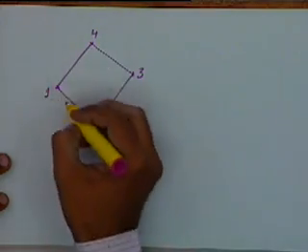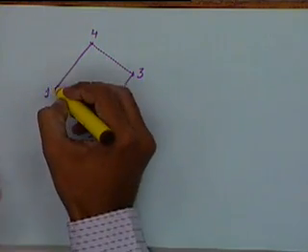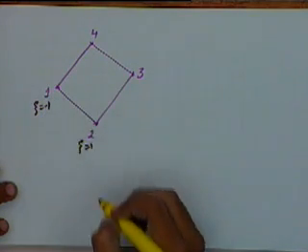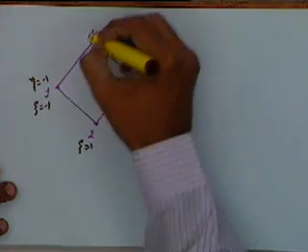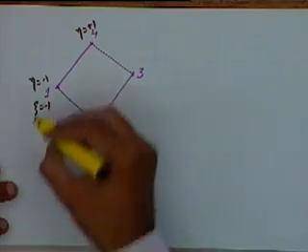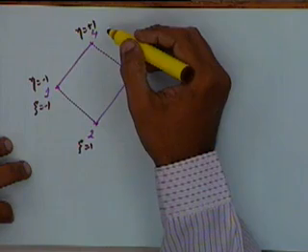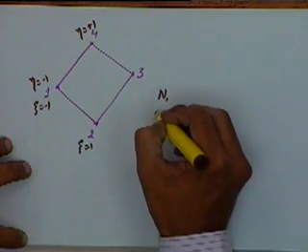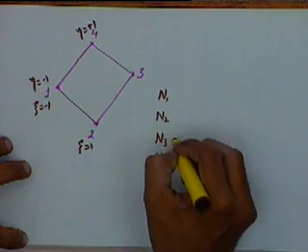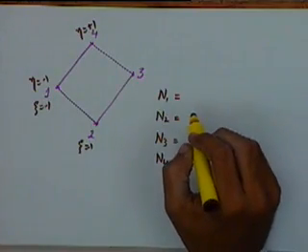And we said that for this 4-noded element, we define a zeta coordinate as zeta equal to -1 here, and zeta equal to +1 here, and eta equal to -1 here, and eta equal to +1 here. So we converted the xy coordinates into zeta eta coordinates, and then we defined the 4 shape functions n1, n2, n3 and n4